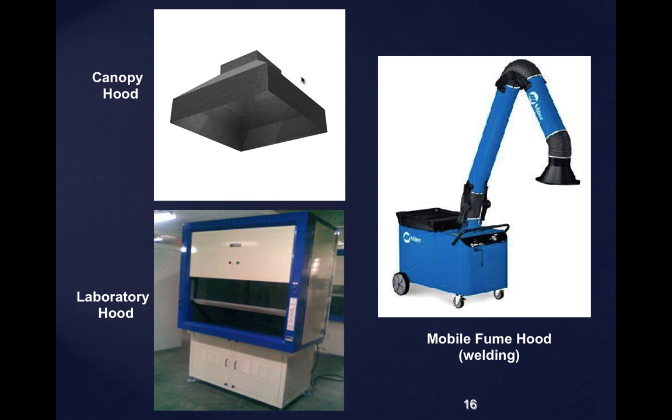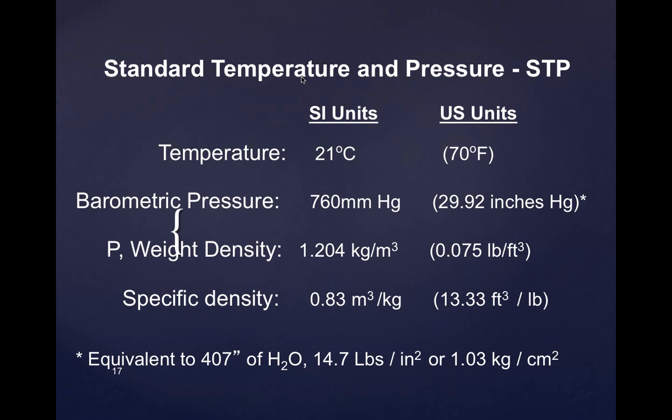We basically see butterfly valves, right? They're in round duct. When they're closed, they completely fill the ductwork, and you can gradually open and close them. We can afford to use them in HVAC systems because the flow rate of air going through the ductwork is much lower. If we used them in an exhaust system, you wouldn't be able to hold them in position. You're moving air so rapidly through most exhaust systems that it would just blow them out of the way, and it would be hard to keep them in position. So on local exhaust systems you see blast gates, and on HVAC systems you usually see these butterfly valves, these control valves.